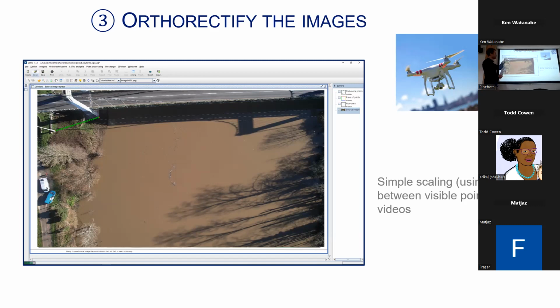Yeah, and you can check that. In Fudaa-LSPIV, you can enter several distances and you will have the resolution associated to each segment. If you do it, you can check that it's working fine if you don't have any lens distortion. And if the camera is not pointing to the nadir, then it will change also. That's what the error is. Once you scale that, and you find out the pixel is 5 centimeters, for example, then the error must be small when you measure your check.